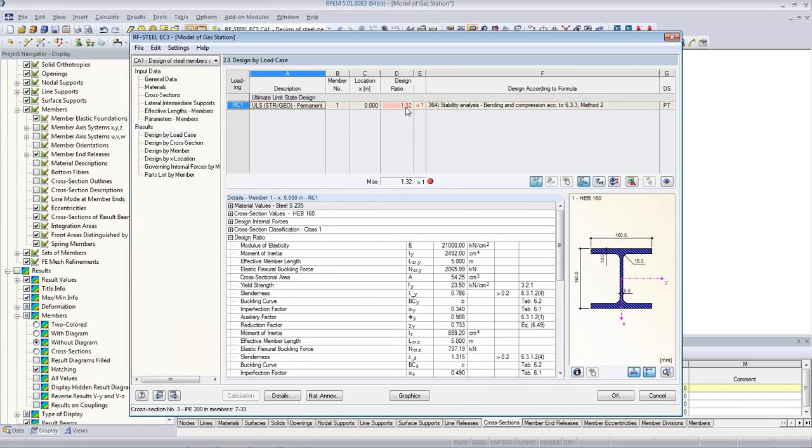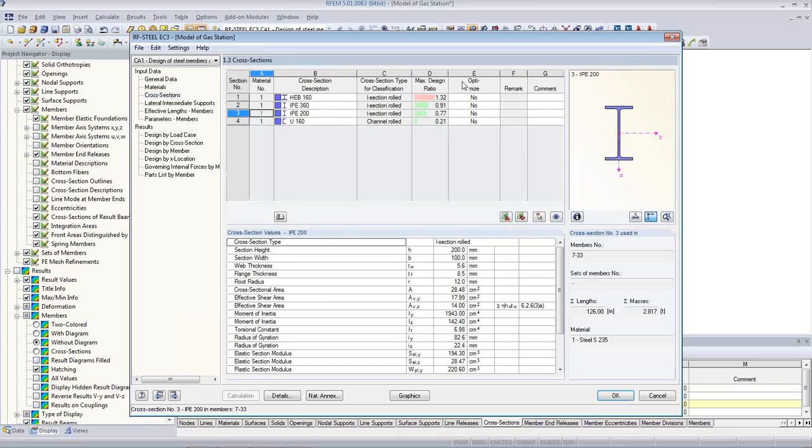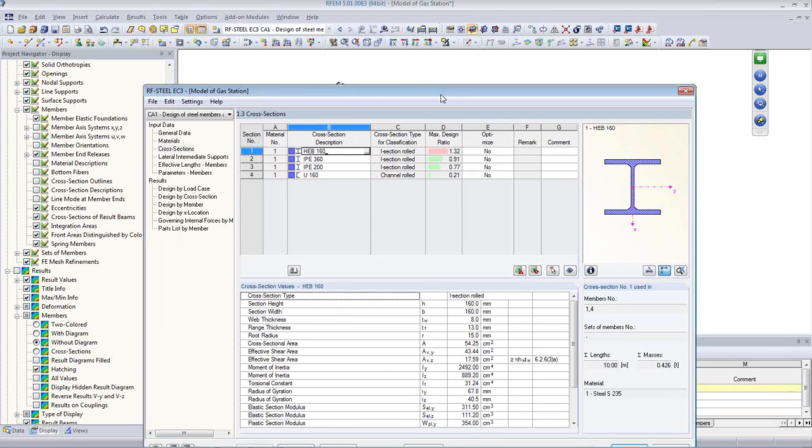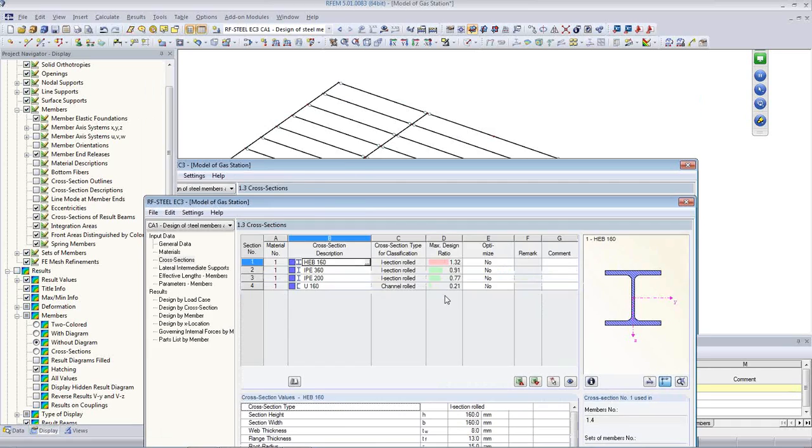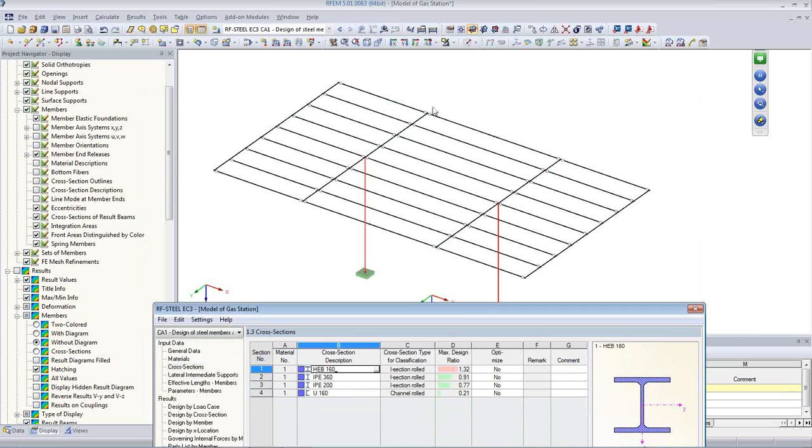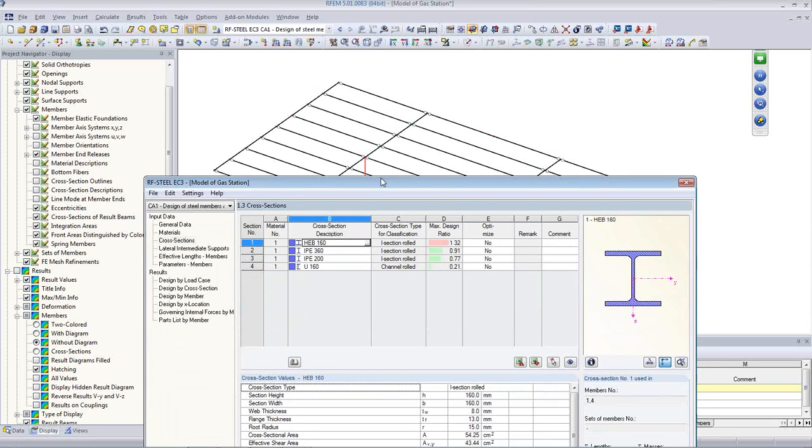We analyzed the optimized cross-section linearly, but we did a nonlinear analysis, so there are some things that are not quite linear, so here we have maybe to do another design round. I have not taken care of the serviceability and the deflections. I know in these cases we have a problem with deflections, because the columns, if they are weak, the whole roof will kind of wiggle back and forth.